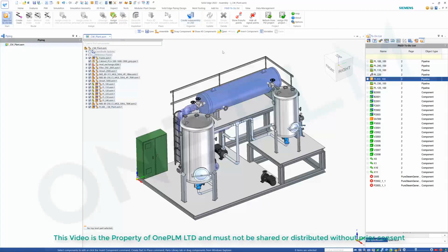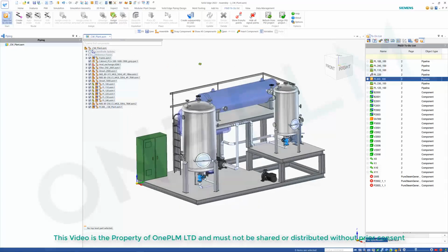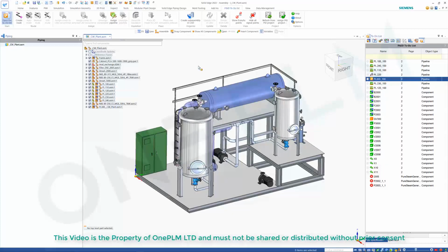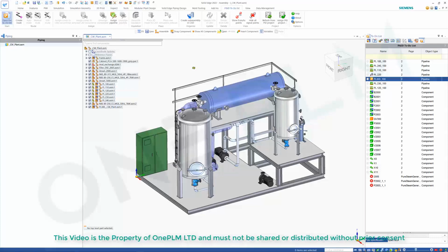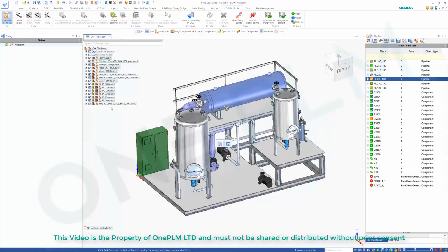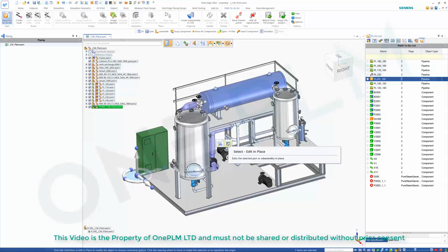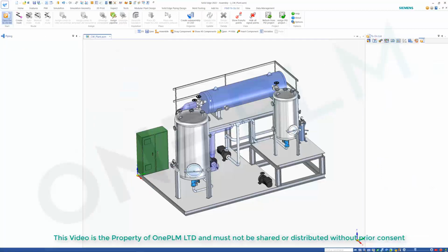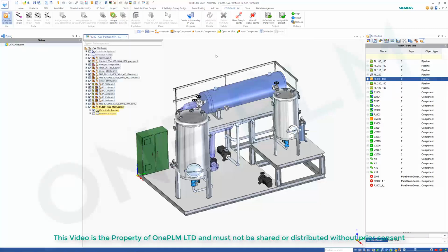If we've got data management, it will run automatically, and it will create it based on the name. So that's PL300, my item number there, and my CW plant on there. If you've got Teamcenter running, that will prompt you to create a document ID for that number using the standard pop-up dialog box. So now we've got that open, I'm going to go and edit in place, because we need references to link the pipeline to the input and output locations.